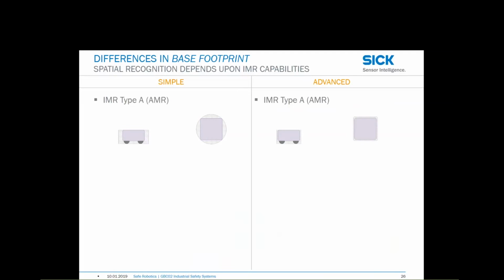This allows the device to have a little bit more understanding about those restricted areas around it. So if we have a type C with a manipulator, you can quickly understand that if I'm not navigating in a really defined, really well understood space, I'm going to need more room to ensure that the clearances around the manipulator are going to be sufficient enough to operate safely.